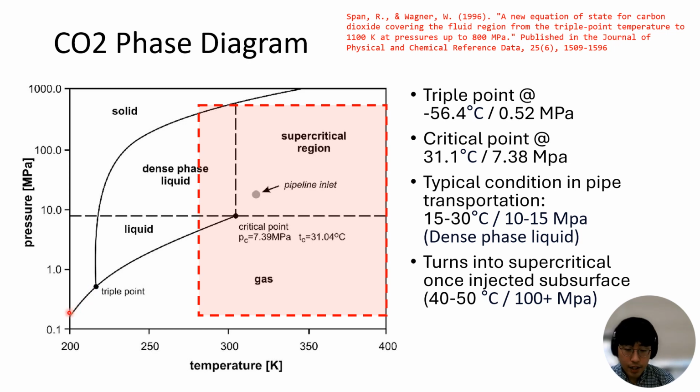If you think about dry ice, it exists at atmospheric pressure, which is about 0.1 megapascal. So at room temperature and room pressure, the solid state CO2 never turns into a liquid when it turns into gas, and that's why dry ice is called dry ice, because it doesn't create any liquid. That's because the atmospheric pressure is lower than the triple point that is given here.